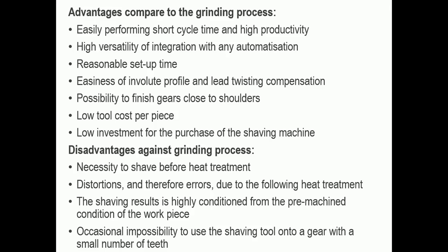The necessity to shave before heat treatment is a primary requirement for the gear shaving process. Distortions and errors occur due to the following heat treatment. The shaving result is highly conditioned by the pre-machine conditions of the workpiece. Occasionally, it is impossible to use the shave tools on gears with a small number of teeth. These are the gear shaving disadvantages.